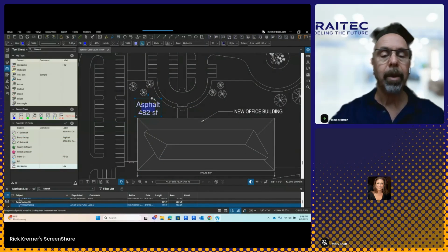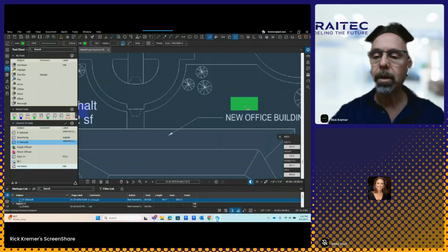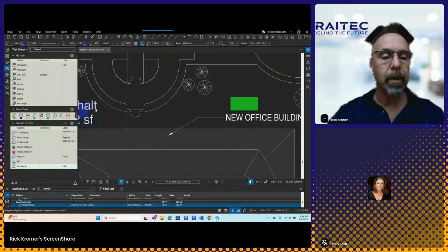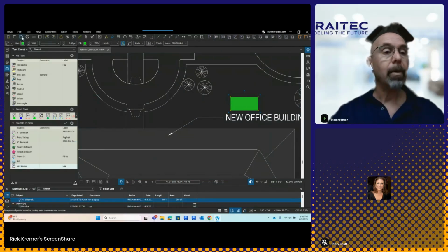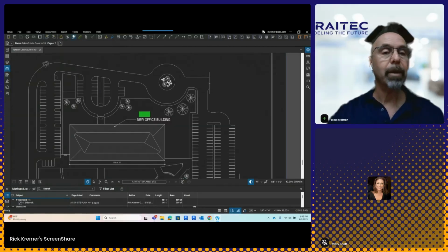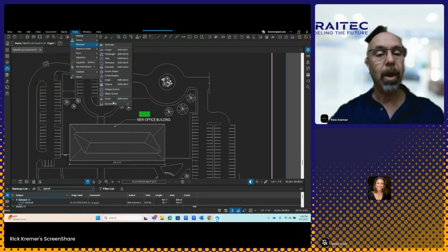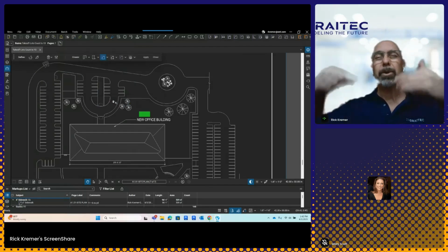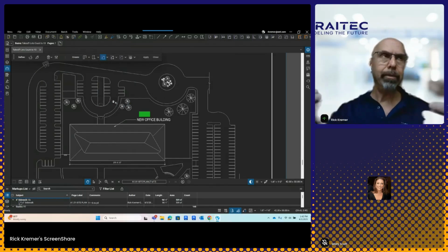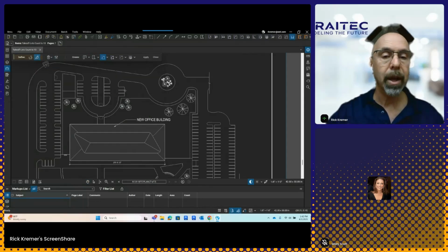Okay, and I'm going to go through and 4-inch. Okay, delete. The reason why I did this is that way Revu knows it's there, and I'm going to go back. Let's go through dynamic fill again. And the reason why is if I were to have placed it, it's going to place it generically, and I want to work smarter, not have to go back and fill in that information.